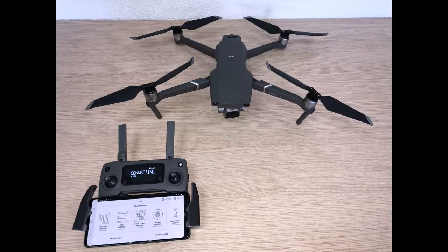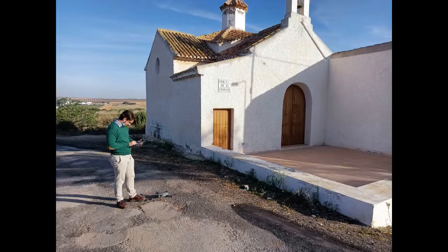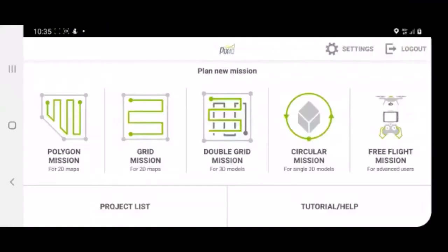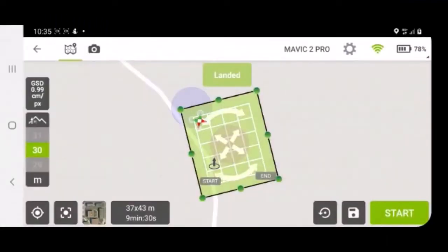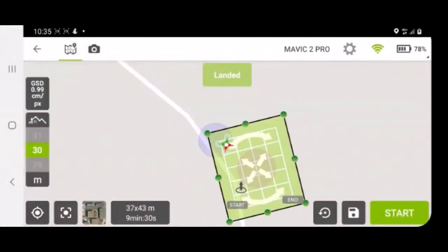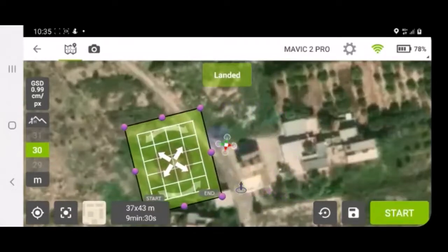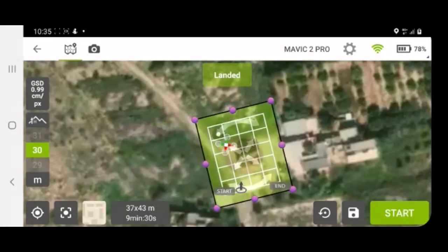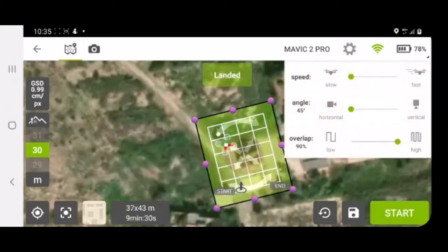Data collection. Drones have become very useful documentation and control tools, equipped with an RGB camera, infrared or LiDAR. The drone used is a quadcopter controlled by a GPS controller with the help of the Pix4D Capture smartphone flight app. On arrival at the flying site, it is important to carry out a ground survey to observe any obstructions at altitude. After making the necessary preparations and connecting the drone, controller and smartphone, the Pix4D Capture application starts and we select the desired type of mission.